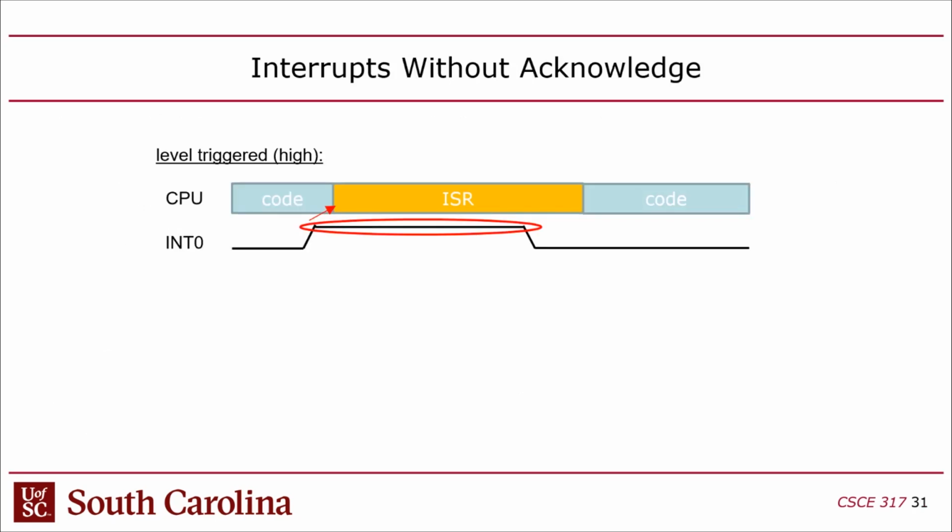Interrupts, we talked about interrupts. There's a few questions on the exam about interrupts. An interrupt is basically a wire that gets the CPU's attention. The problem is, how does it do it? There's different mechanisms. Not all interrupts are the same. An interrupt is a very generic term that just says, I have a wire that gets the CPU's attention, but how does it actually do it?